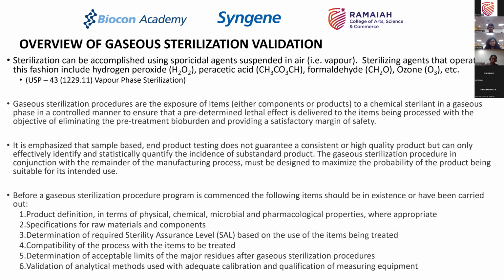You cannot sample the whole batch, otherwise your whole batch will become non-usable, because sterility testing is a destructive form of testing. So you will draw only samples, but when you are doing a gas sterilization process, you have to ensure that the upstream and the downstream of these process are also validated time and again, so that you are 100% sure that you have not introduced any contamination even by mistake.